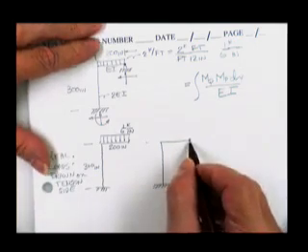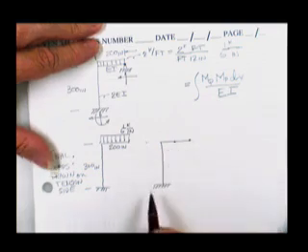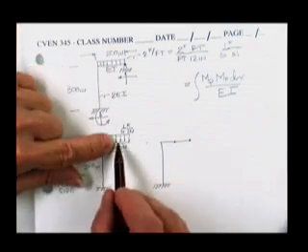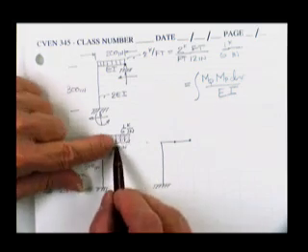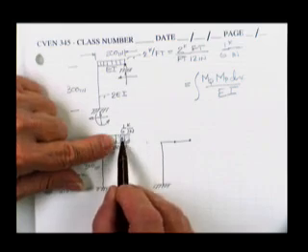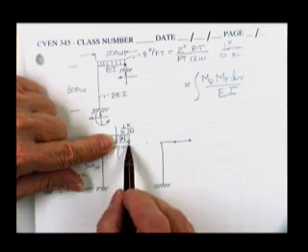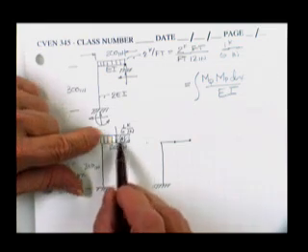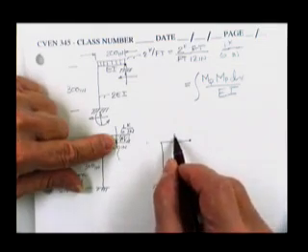This will be 0 in the middle of the beam. The moment will be 1/6 tall times 100 wide times the distance from the centroid of the load past that point, 50. So the moment's going to be on the tension side.